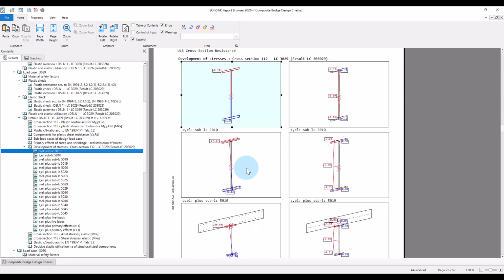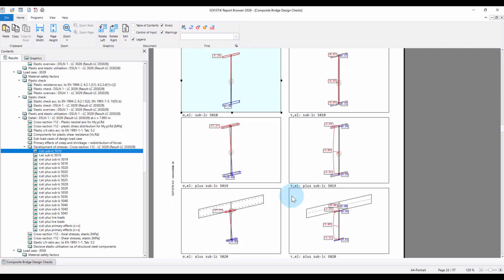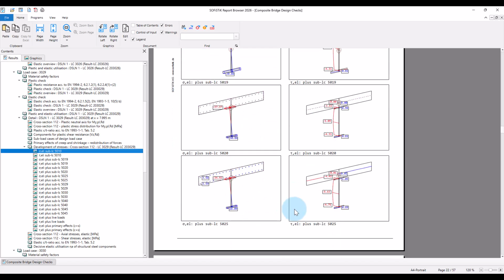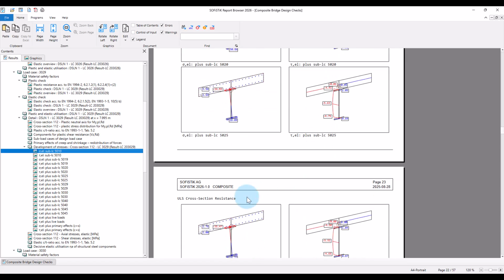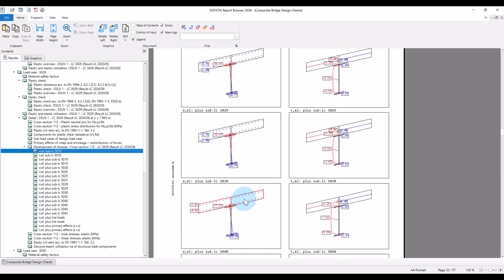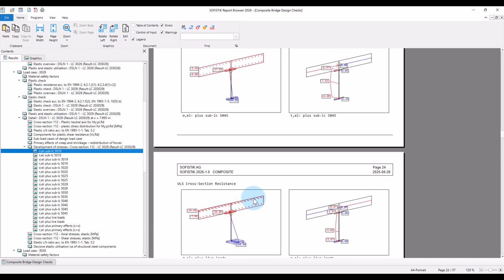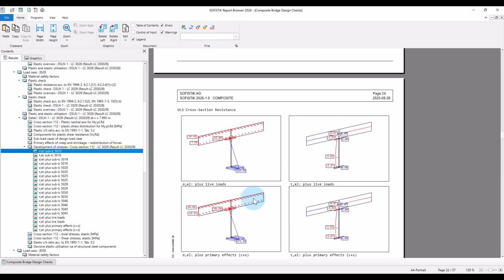First, we have the pure structural steel section active. Here on the right axial stress, the left axial stress, on the right shear stress. Now the concrete hardens. Further loads get applied on the now full composite section. And then we get to the live loads.